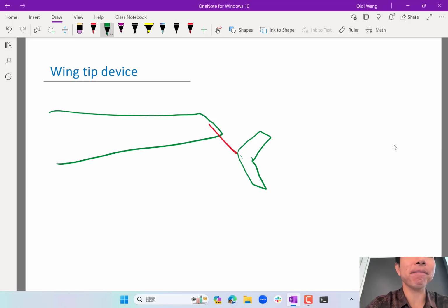If the flow goes around the vortex like this, the winglets have to oppose the swirl of the flow, so that it needs to produce a lift in the direction over here on the upper side and create a lift in this direction on the underside, right?